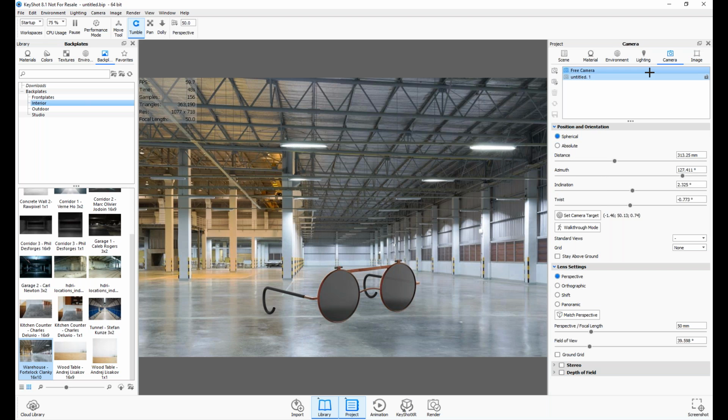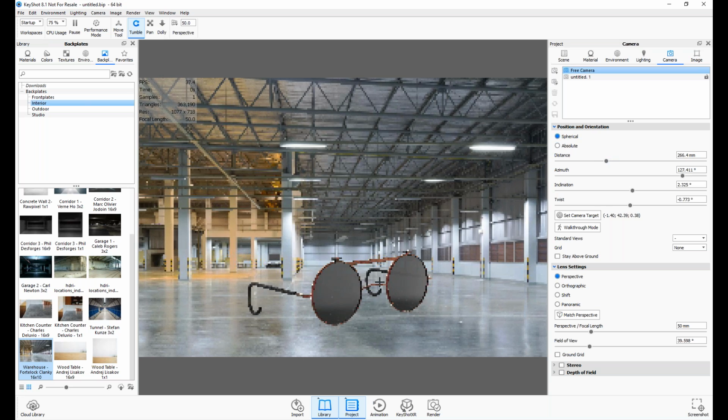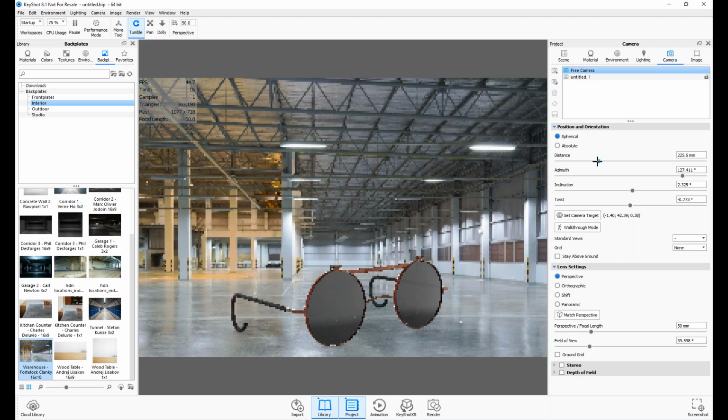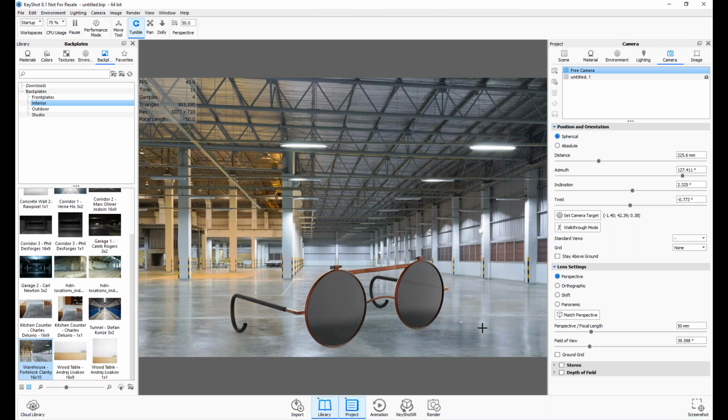But then we have the camera tab. Within the camera tab, we can configure our specific cameras. We can always add our own new cameras and specify those cameras for different renderings. We also have the ability to specify the camera values. So maybe I want to zoom in and I want to do this with some kind of accuracy. I can always perform that here in the environment.